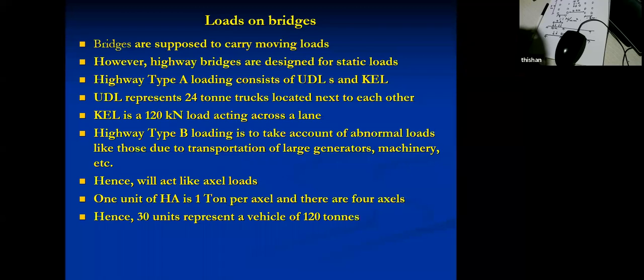So if you have designed for 100, 120 or 180 ton vehicle, and our actual vehicles are in the range of 40 tons, you can see there's a huge inherent reserve capacity in bridges. So if you design a bridge with a great deal of care, you will find that those bridges are actually very safe. So if you are a bridge engineer, if you have performed the load evaluation properly and got a reasonable system to resist bending moments and shear forces, then the chances of anything going wrong are pretty remote.